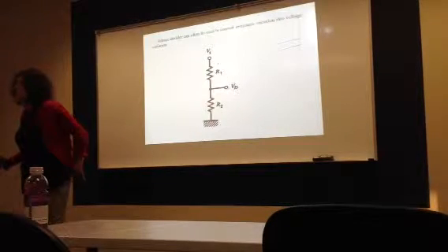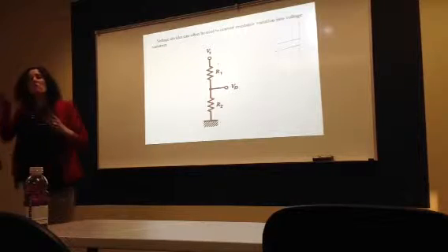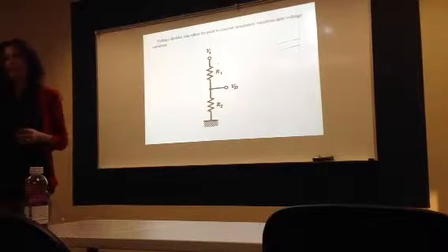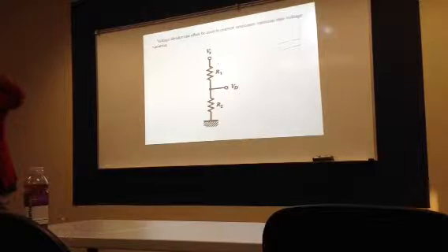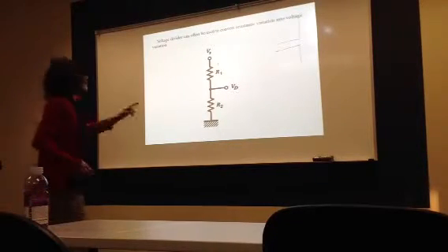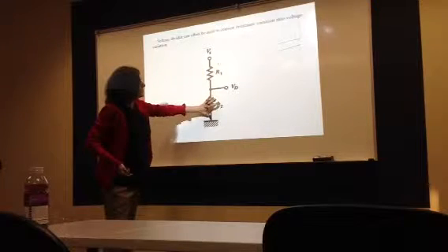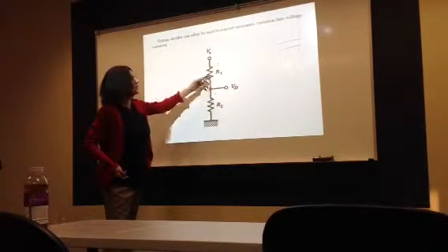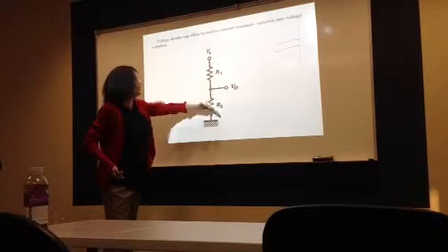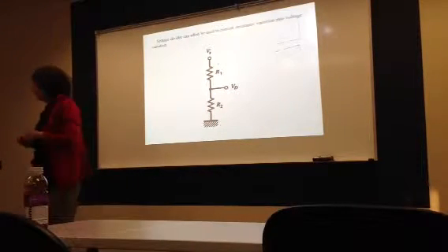Chapter 2, we talked about analog signals. Voltage divider, we used it for what? To vary the resistance. Remember the Wheatstone bridge? We had the RTD, the sensor, to sense the temperature, and it gave us variation in the resistance, and we were able to switch that to a signal, and then we fed it to the analog input module, which is A to D. So VG equals this voltage times R2 divided by R1 plus R2, and if R1 equals R2, and we have 10 volts here, we have 5 here and 5 here, and we know how to deal with that. Okay?